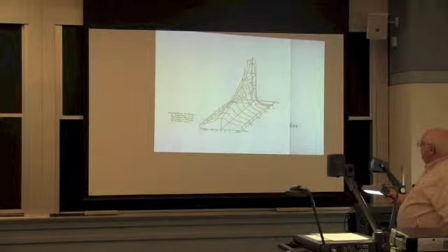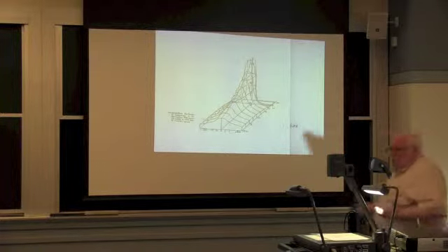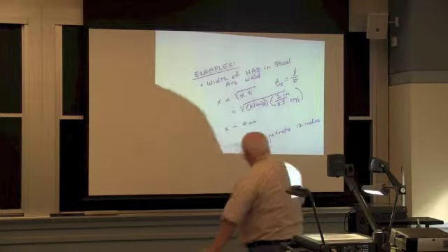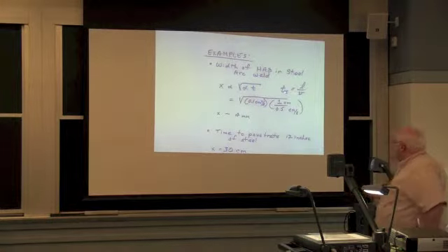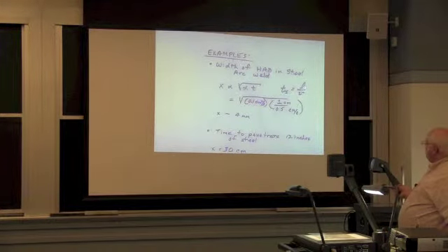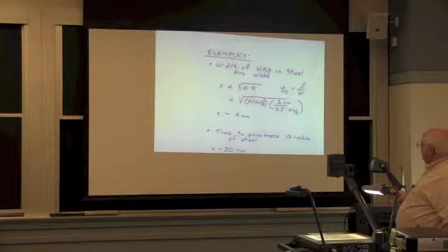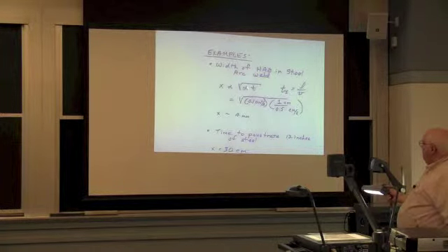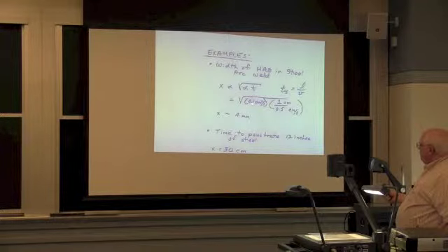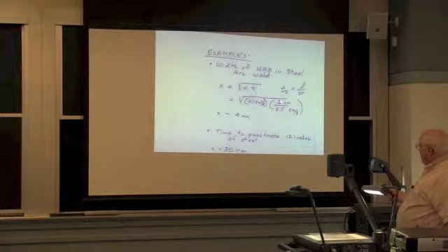And if I say the size of the arc weld pool is about 1 centimeter long, because 1's a convenient number, then the interaction time is 1 centimeter divided by the velocity. A typical arc weld might be going at 0.5 centimeter per second, and I have for steel 0.1 centimeters squared per second times 2.